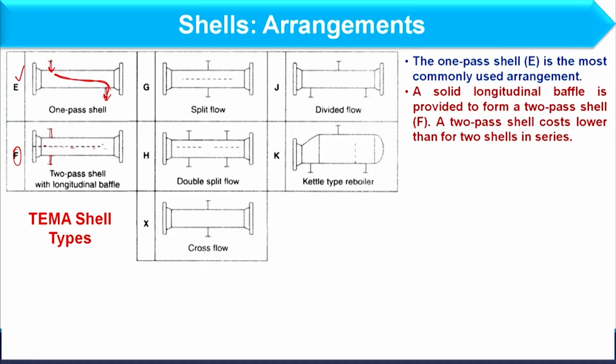So, in this baffle sometimes holes are provided, fine. So, these holes basically work for the condensation process, okay. When the liquid is flowing, the holes are not required over the baffle, okay. However, holes are required, or we can call that a perforated baffle, right. So, through this perforation, condensate of the vapor can pass through easily, fine.